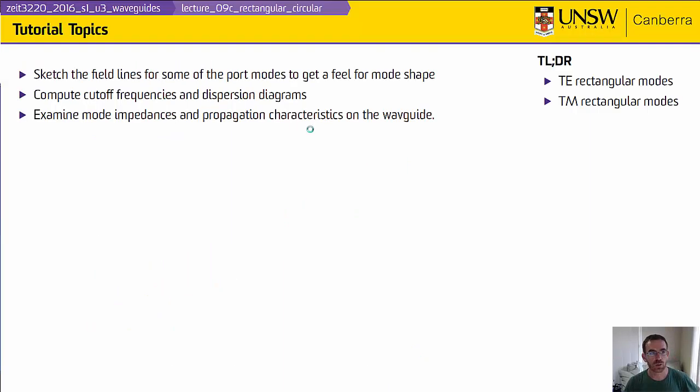So to conclude the tutorial topics, we're going to ask you to sketch the field lines for some of the port modes so you can get a feel for mode shape. Compute the cutoff frequencies and look at the dispersion diagrams. Understand where you want to operate.